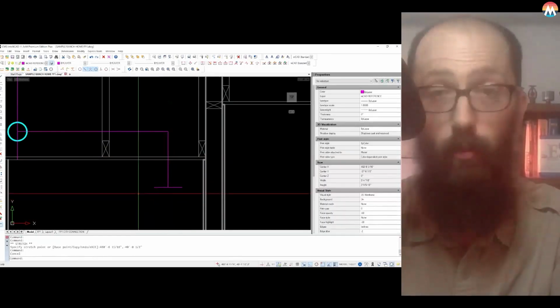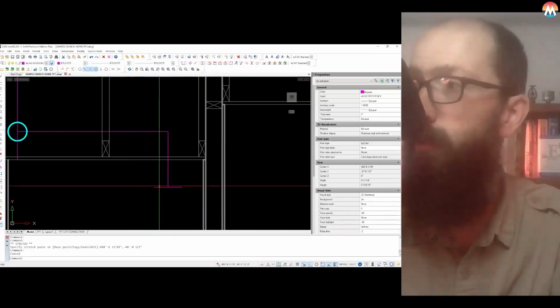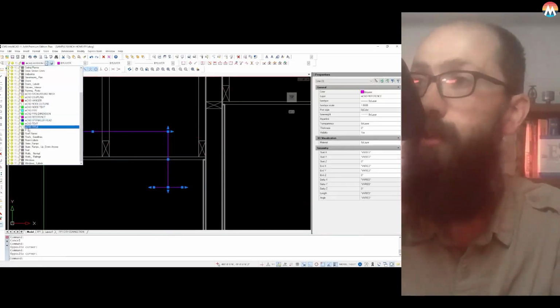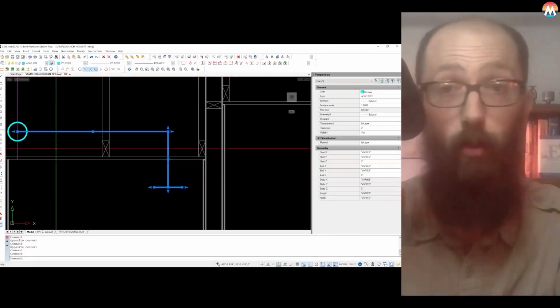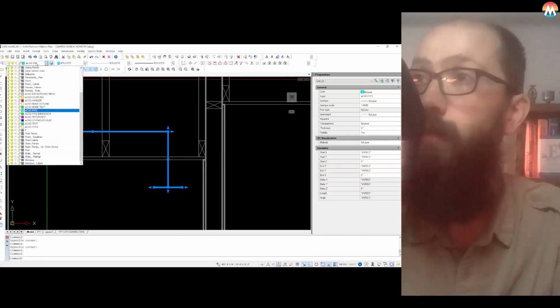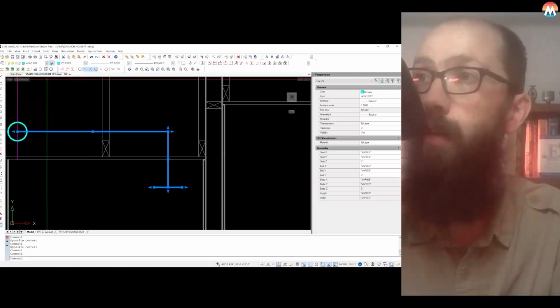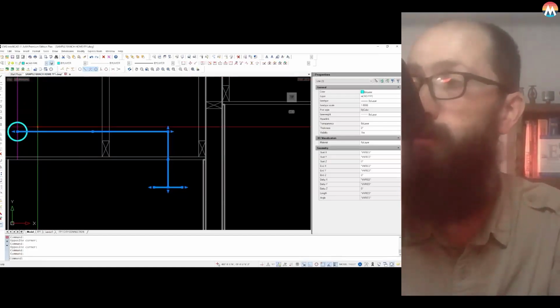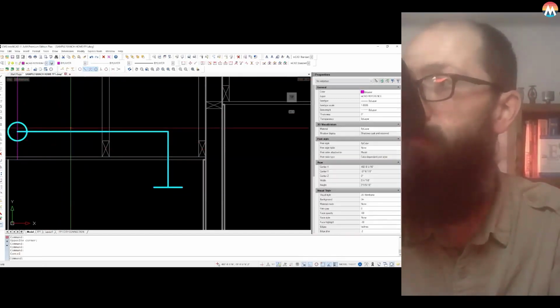And that's representing a sprinkler. Now I'm going to select all of these. I've been using construction lines, mCAD reference, to draw it. That layer won't print. I just selected them and put them on mCAD pipe by selecting mCAD pipe from the drop-down reference here, from the layer tools that I have up here.